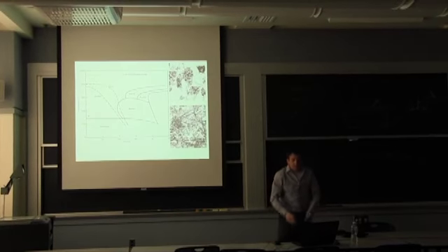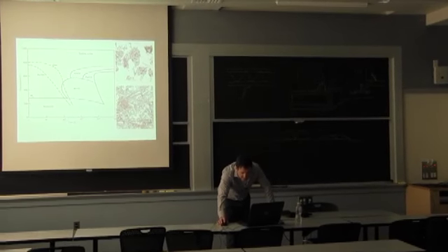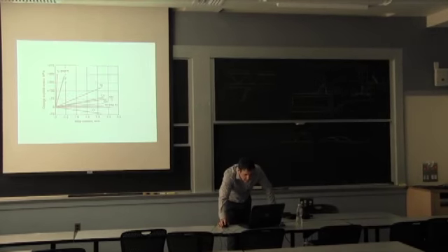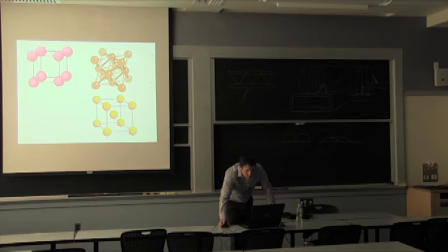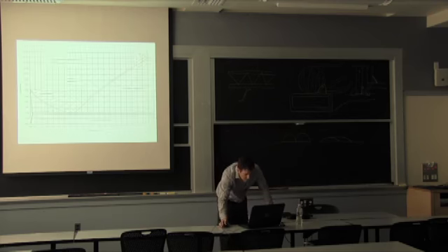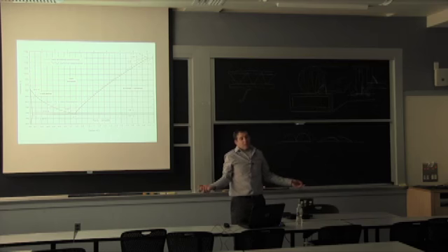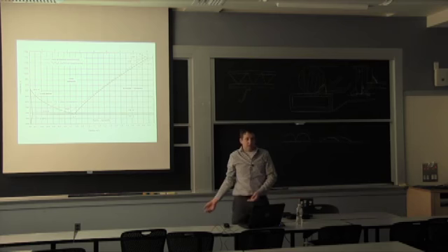So we're going to go to martensite now. Martensite essentially is what happens when you cool very fast. And what happens is you go out of equilibrium. The martensite, you can look at it in this phase diagram. You know, we have the cementite, we have the alpha phase, the ferrite here, we have the austenite. There's no martensite. The reason is it's not an equilibrium phase. It's something that happens because you don't allow for something else to happen.